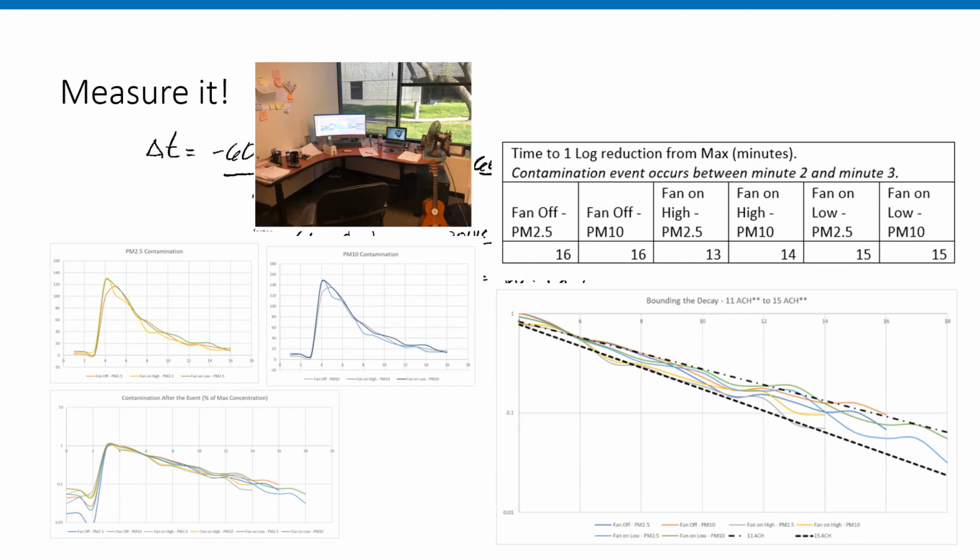Well, that would be my office. I sprayed my office full of Aquanet hairspray and took readings every minute and then plugged them into the equation. I calculated the equivalent air change rate, and you get between 11 and 15 air changes per hour. But I work in a leased landlord-owned office park with just standard issue rooftop VAV units. I assure you, my office does not have 15 air changes per hour.